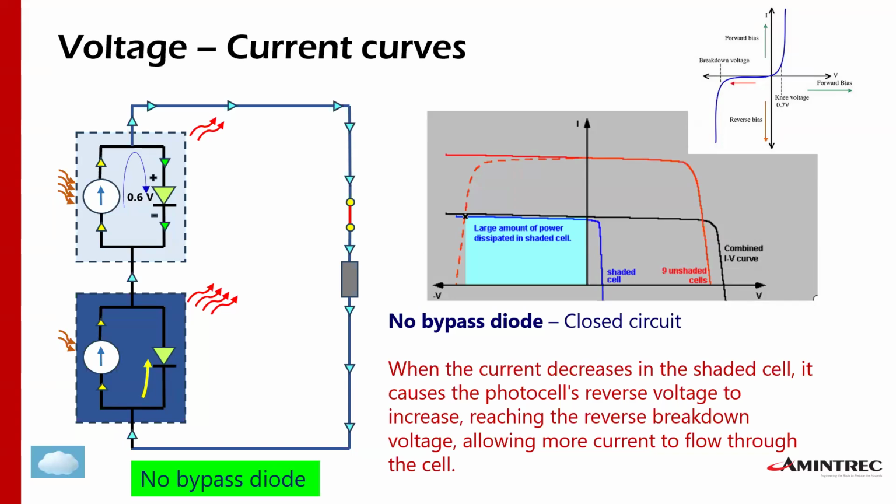Okay, that will damage the diode, of course, and I will have more current over here, and that will increase the temperature of the cell. Okay, very rapidly, because I'm going to have a lot of negative current going the other way, more than on the other side. So that will increase, and it will increase this one as well, because they're connected in series, and these two will increase the temperature. But this cell will be at a higher temperature.